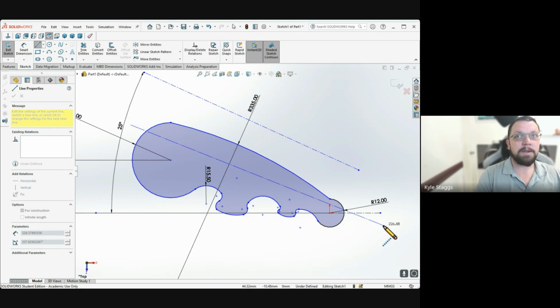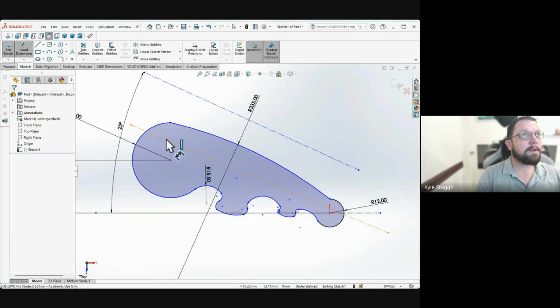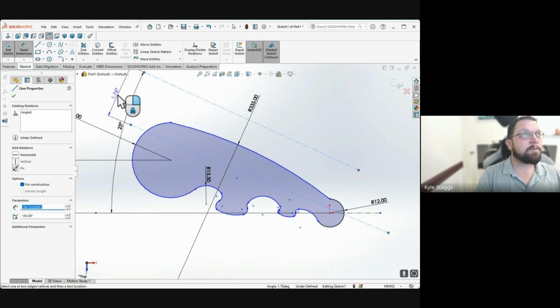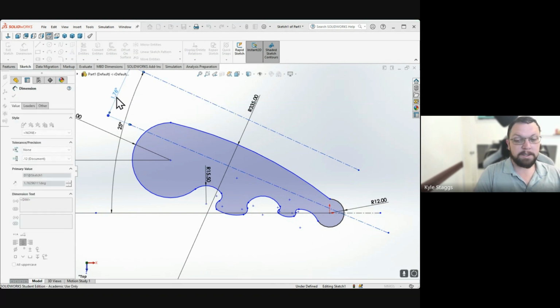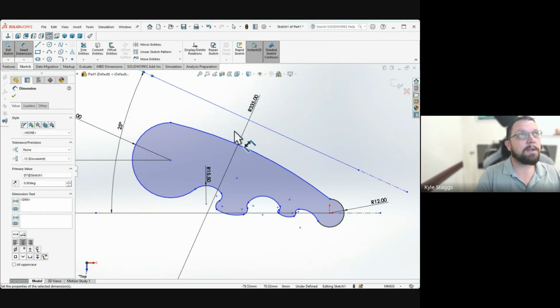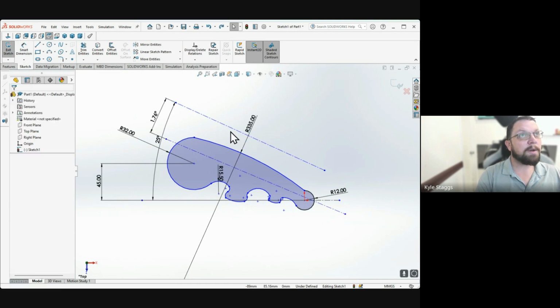You can bring it down here through the part as needed. I just want to not have it associated with any of these other anchor points or reference points because I want to change all the dimensions of those. And I want to set the angle reference to 0.